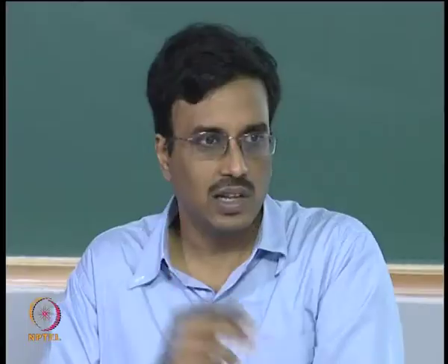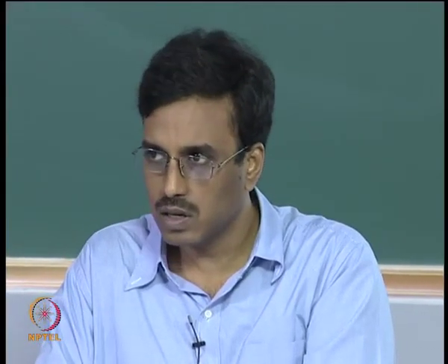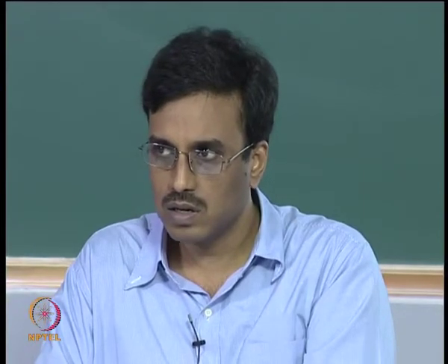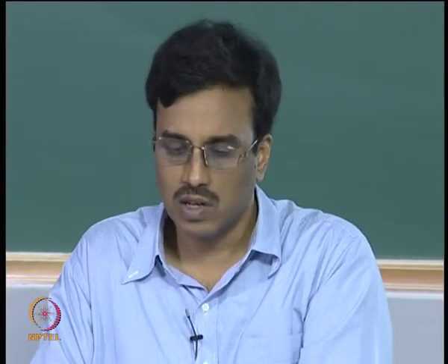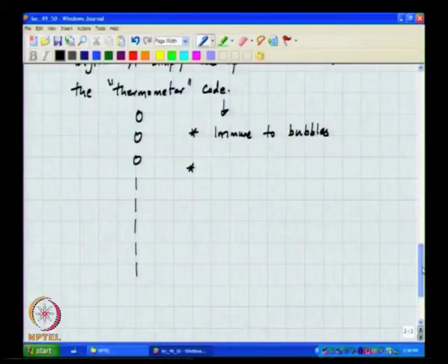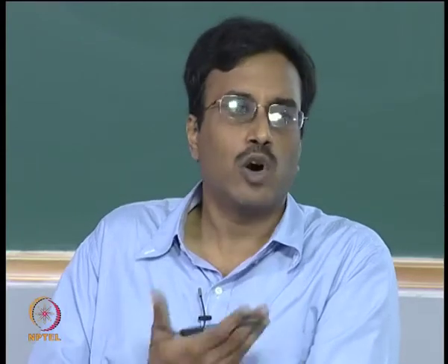Pardon? Think carefully. Let us say the offsets in the comparators were very large. No, that is not what I am asking you. I am asking you, can you comment on, I mean in a regular flash converter where we have the thermometer code and the usual bubble correction logic, etc. If there are big offsets in the latches, offsets larger than an LSB for example, can you comment on what happens to the output code of the flash?